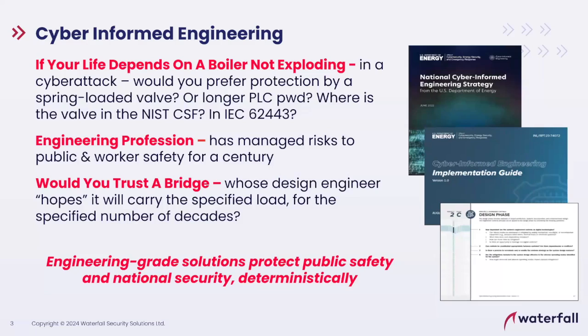These are all cybersecurity standards. The overpressure relief valve is an engineering mitigation for unsafe conditions. It's never going to be in the cybersecurity standards. It is a tool that is available to manage physical risk. And it's applied routinely. These valves are installed routinely on these boilers to deal with the risk of an earthquake coming in and crimping, collapsing the outlet pipe on the boiler, trapping the steam in the boiler and causing the boiler to overpressurize. They're designed to deal with the risk of a hurricane coming in and blowing too much oxygen into the furnace and overheating the boiler and overpressurizing the boiler. They're designed to deal with physical risk to industrial physical operation.